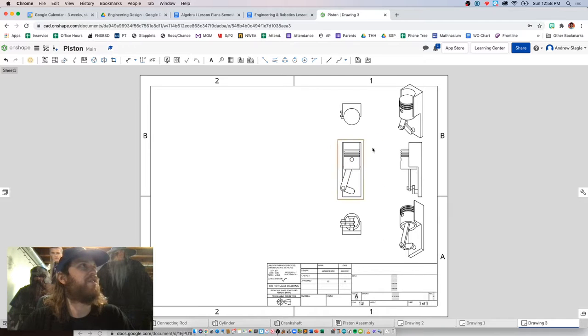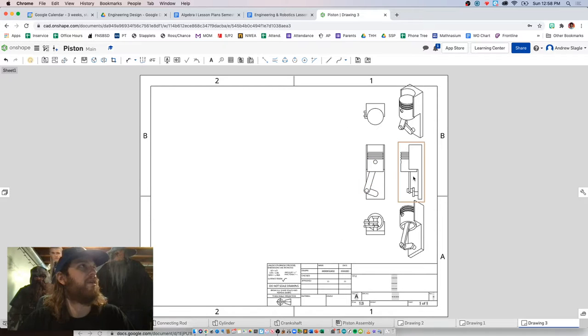If I shift this over, you notice the top and bottom view are kind of aligned. If I shift it down, the right view shifts down. So you can kind of position all the drawings simultaneously. We get this nice view of our assembly. So great, that's what the projected view does. So the projected view allows you to get those basic views of the assembly going.